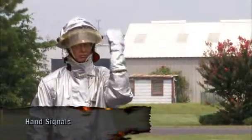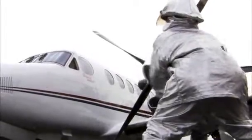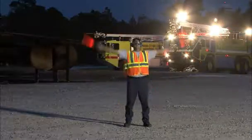ARFF personnel should be familiar with standard emergency hand signals for evacuation recommended, stop recommended, and emergency contained. Give signals from the aircraft's left front side as seen by the flight crew, and use wands at night.